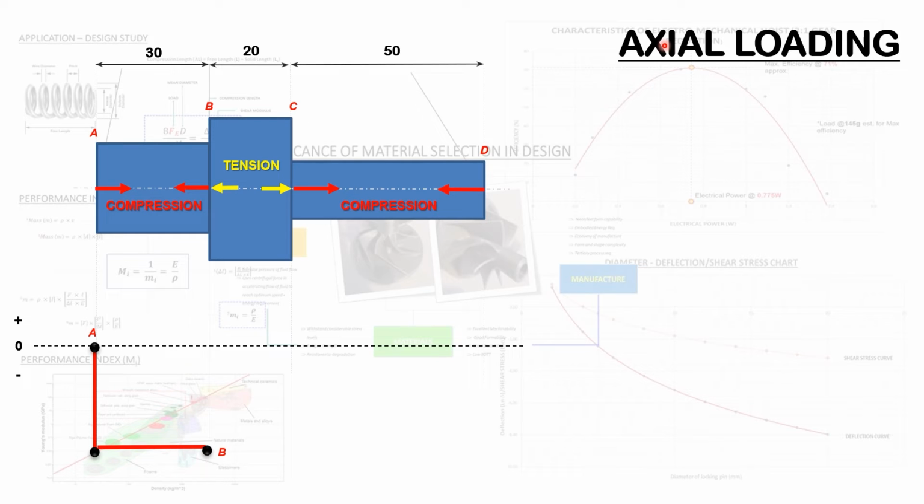Okay, so since there aren't any forces along the cross-sectional profile of AB, we are going to assume that that force is constant throughout until we get to interface B, where we have the 15 kilonewton force acting to counteract the 10 kilonewton force.